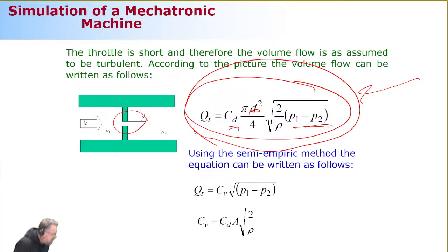That's why there's an alternative. The alternative is based on just measurements. You do nothing but measure different components, and then you define how a component behaves under different configurations. How it behaves at different pressure values, how it behaves when the spool position is this and that, how it behaves when the spring's initial force is this and that. You're creating a kind of library, which you can call a lookup table. A lookup table says these are all the possible input parameters, and the corresponding behavior is like this. This is called the empirical approach.